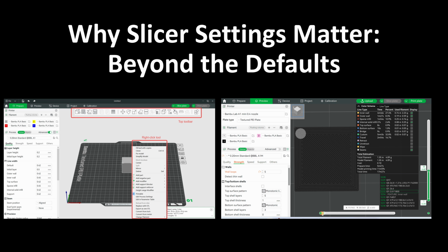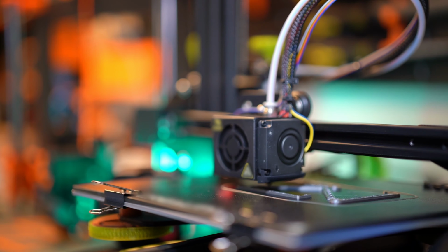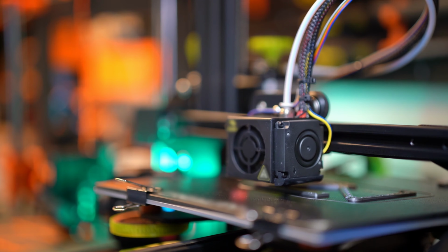We are talking about things like layer height, infill density, print speed, support structures, and adhesion settings. Get these wrong, and you will face warped prints, weak parts, or even total print failures. But get them right, and you'll achieve stunning functional results. It's like fine tuning an instrument. Small adjustments make a huge difference.